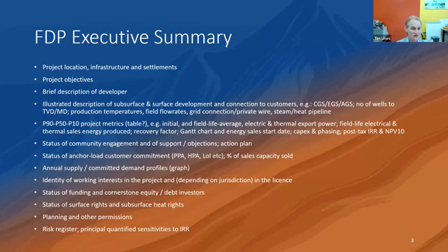The other thing is that it's one thing to have production capacity; it's another to be able to sell your gas, your heat, and your electricity in anything like a constant manner. Because unless you're in a very large grid, then you'll see that the supplies are very, very volatile. And some days you'll have very high demands, and others you won't, or other hours you won't. So it can be hour by hour differences in productive capacity, and that then affects the way you design your surface facilities.